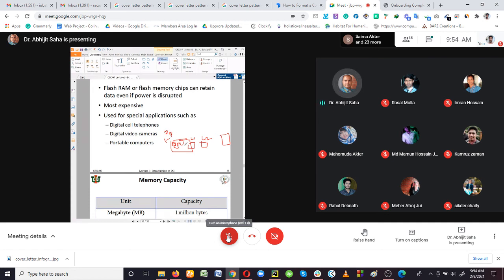So for that 8, it is going to check the L1. If the L1 has this 8, it is going to respond immediately. But if it is not there, that means it is a cache miss. It will move to the L2. So it is now going to check whether the required 8 operand is there in the L2 or not. If it is there, then it is going to respond immediately, and from the L1 it is going to be given to the CPU.